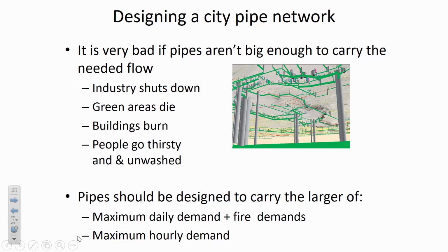But in contrast to that, the water demands at the food processing plant are probably pretty constant because presumably there's some sort of an industrial process there that's in continual operation. And I told you, I think, how many million gallons of water per week is used at that food plant. Now, it's probably not used 24 hours a day, 7 days a week. At least that's not the conservative assumption. The conservative assumption would be that the water is being used maybe 40 hours per week. So you have a fewer number of hours that volume of water is being consumed, and so that's going to increase the flow rate going out at that location.